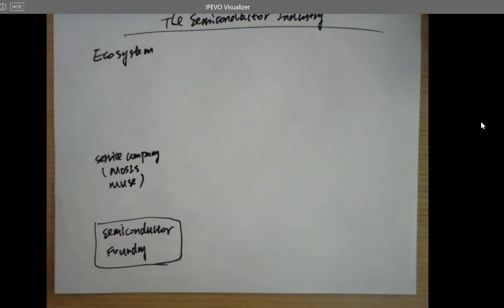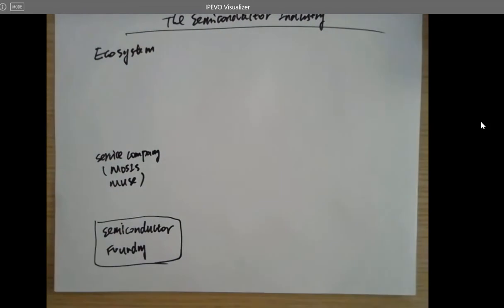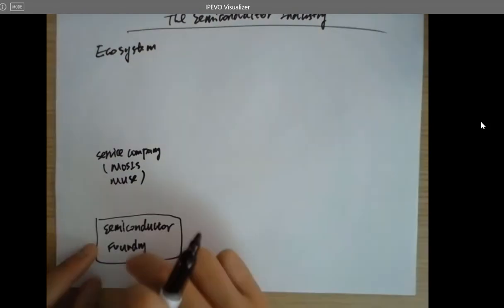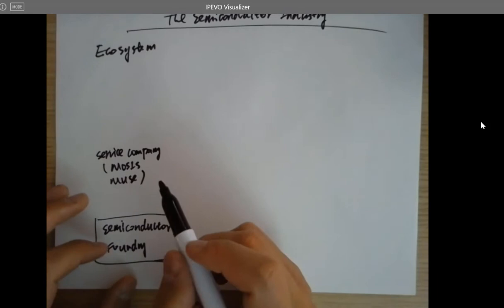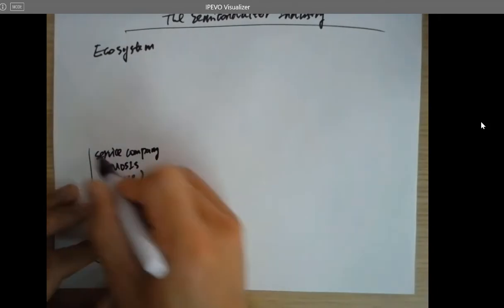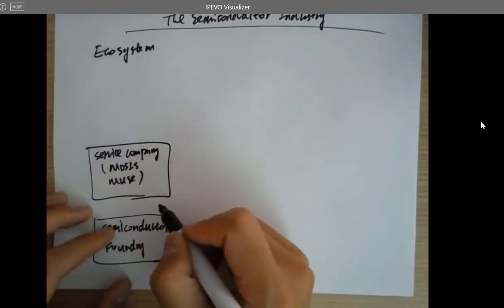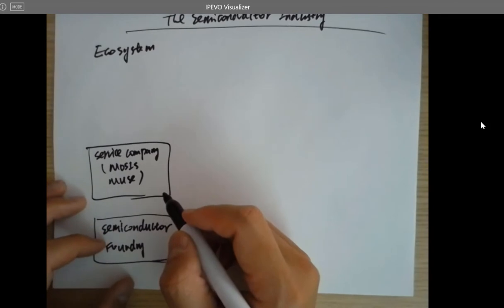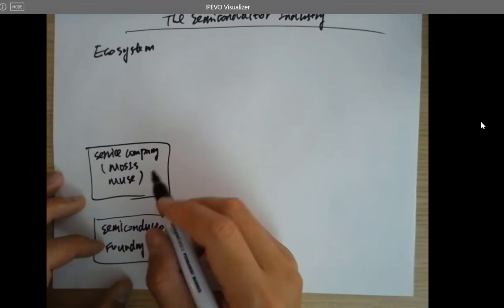So it doesn't make sense if one customer only wants to prototype about 10 dies and you directly use one wafer for the fabrication. So normally these companies will collect all the different designs, so you can send them to the foundry at one time, and reduce the cost. That's how we fabricated our chip two years ago, with the analog circuit design, with no cost.